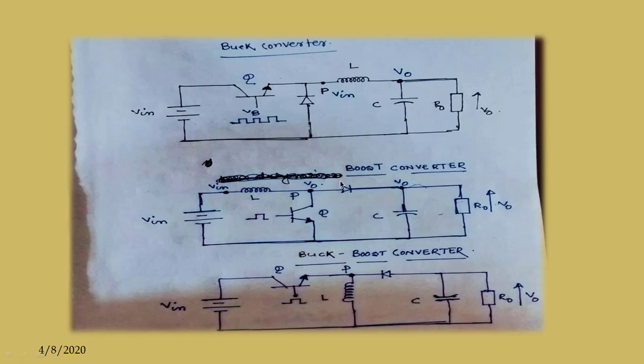And in the boost converter we have to keep one thing in mind: when this BJT is off, the inductor starts discharging through this path.